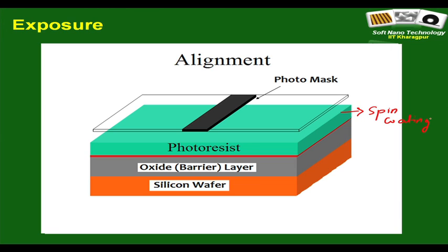What is the next thing to do? You bring in the photo mask. Looking at the geometry, you understand that you had started off with a chromium coated glass, and over these areas the chromium layer has been stripped off.